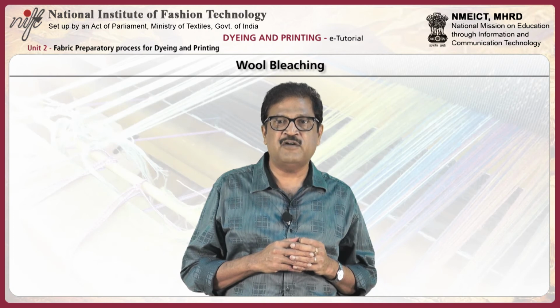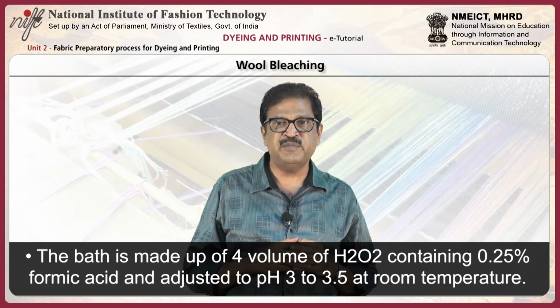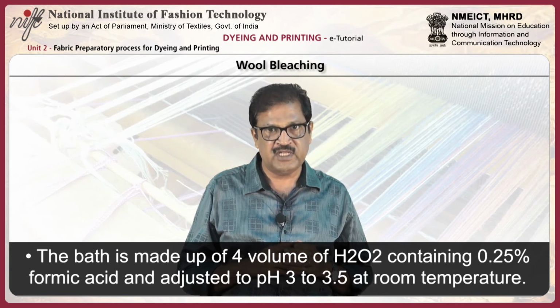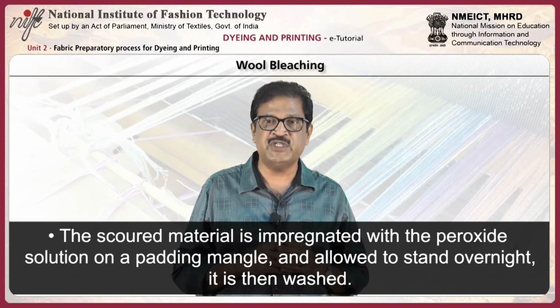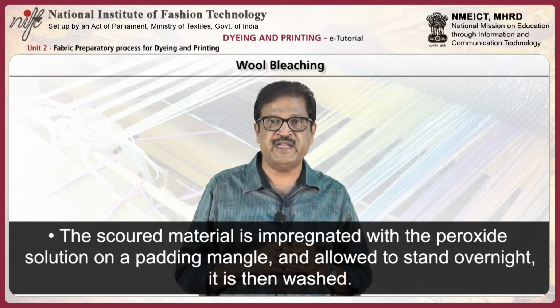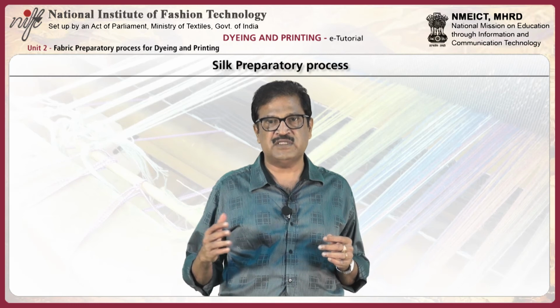This is a method of peroxide bleaching under acidic condition. The bath is made up of 4 volume hydrogen peroxide containing 0.25% formic acid and adjusted to pH 3 to 3.5 at room temperature. The scoured material is impregnated with the peroxide solution on a padding mangle and allowed to stand overnight. It is then washed.